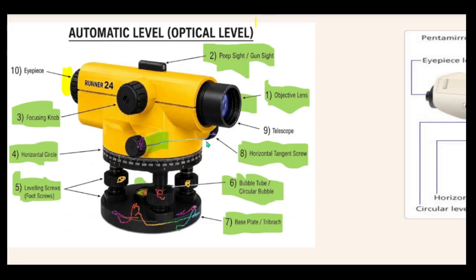Now they help us because this leveling instrument can shift a very little. When you notice it, you use these screws to adjust to a precise direction horizontally of this whole leveling instrument to sight your object very well.